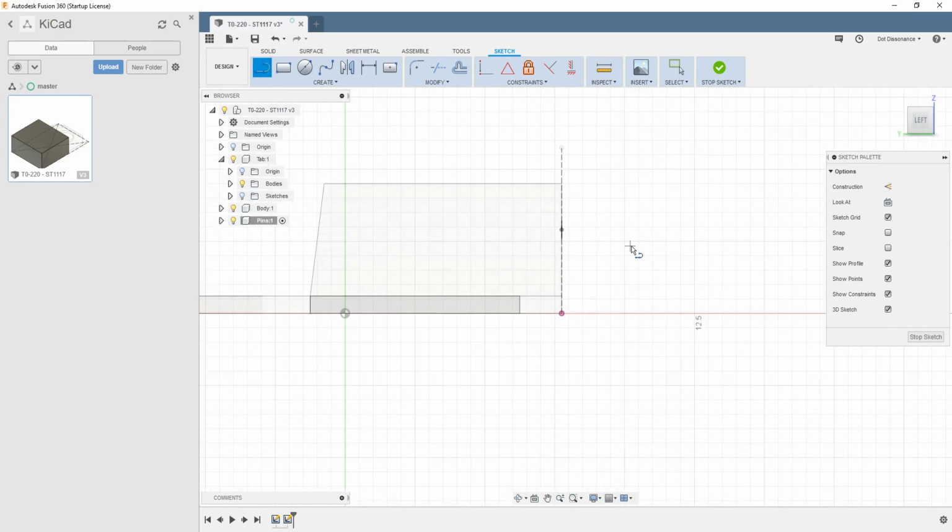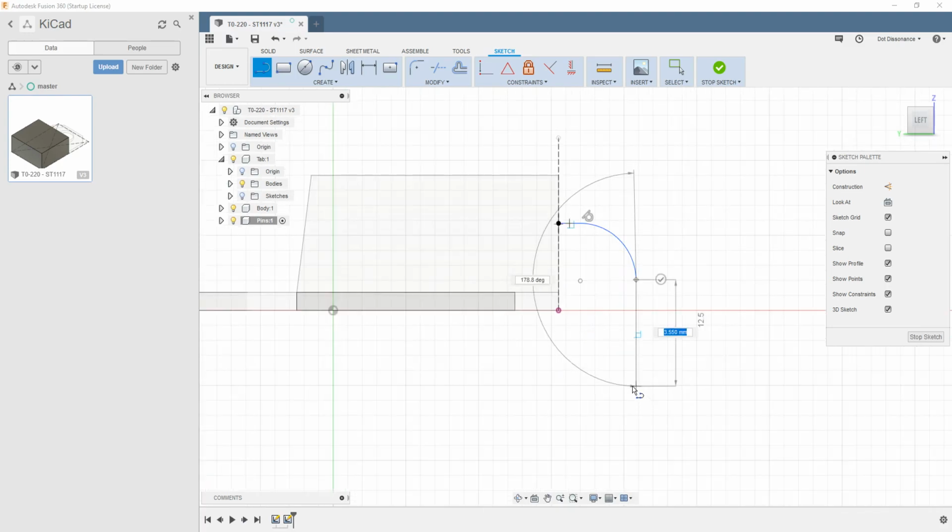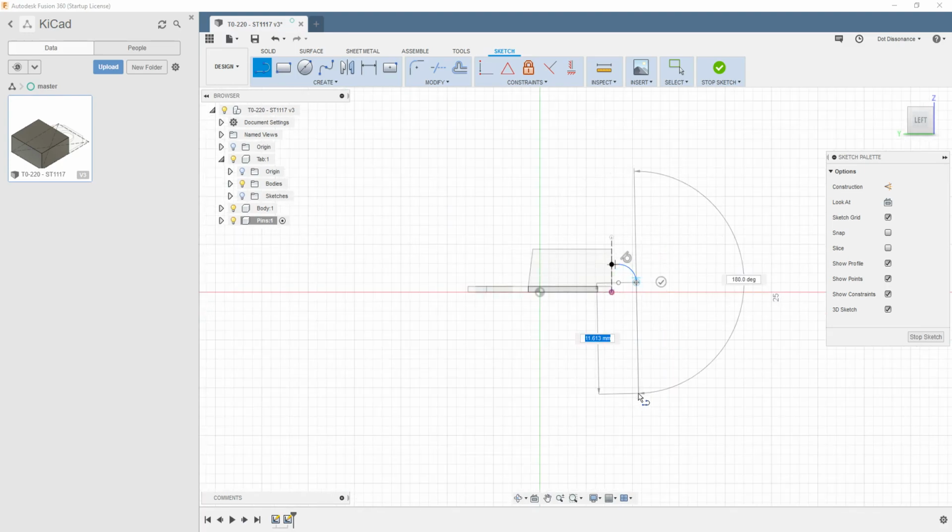A couple things are going to happen here now. I'm going to snap to this point, click, and I'm bringing it out like you would imagine. Now, you might not know about this, but don't click. Get it straight and then just hold it down. I'm holding it down, and you see how I'll make a little curve. I'll bring it out here, somewhere out here about like this. Let go, and then zoom out and bring it down. If you want to make it tangent, it's kind of either or. You bring it down here and then clip that off. So it's tangent, so I don't have to make the tangency, but it's not straight, so I got to make it straight. So whichever one suits your fancy there.